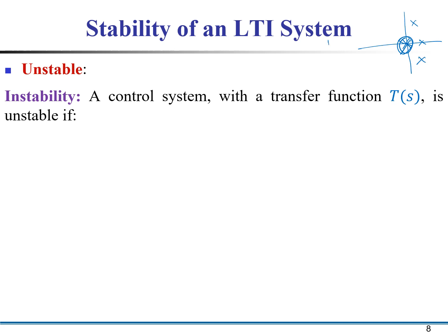And these multiple poles can appear on a single location at the origin, or they can be in any other place on the imaginary axis, like here, plus j omega and minus j omega. If there is one pole over here and one pole over here, they will not generate an instability in the system. But at the same location, if there are more than one pole, then the system will be unstable.